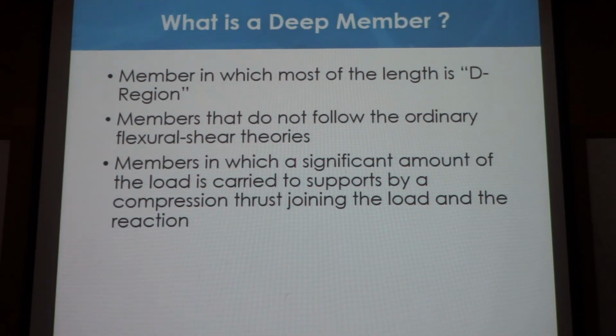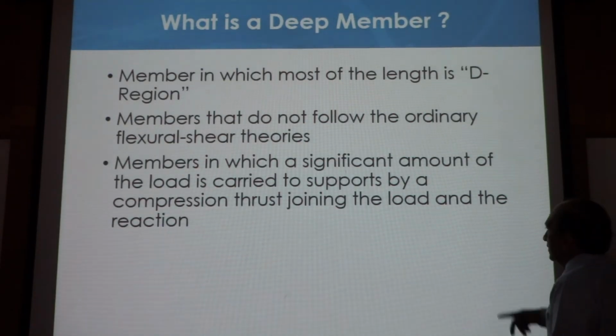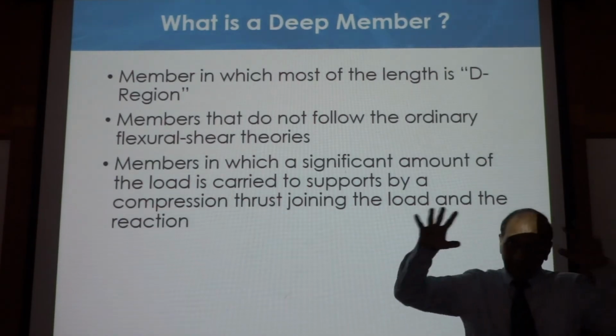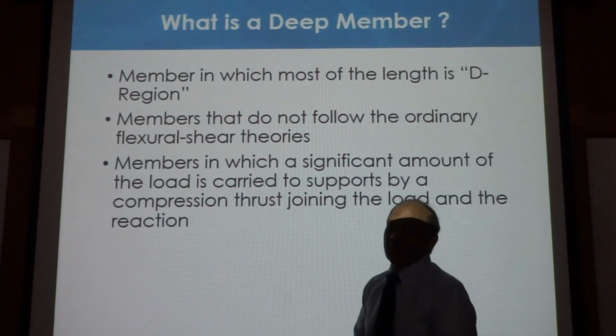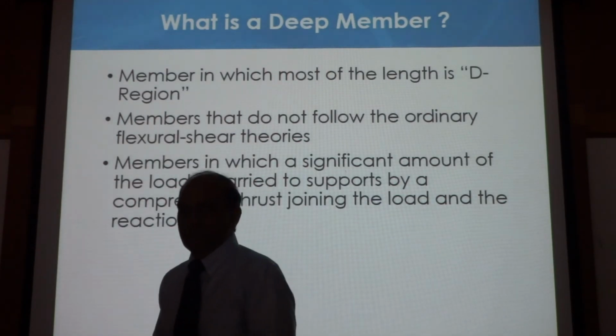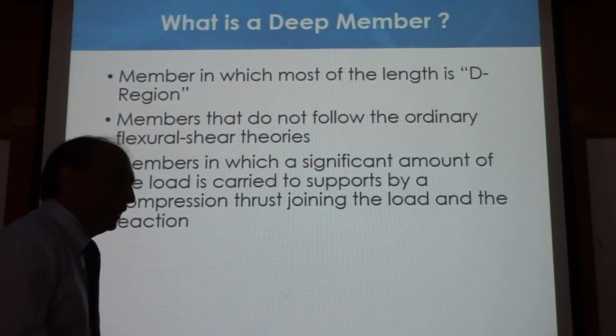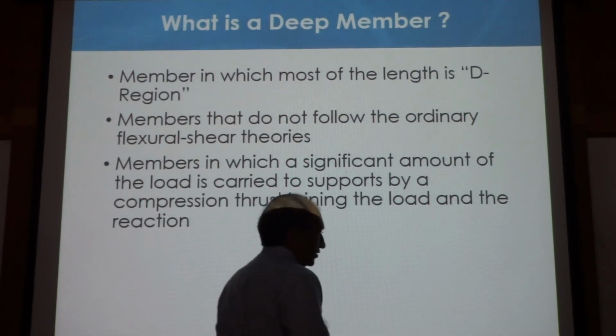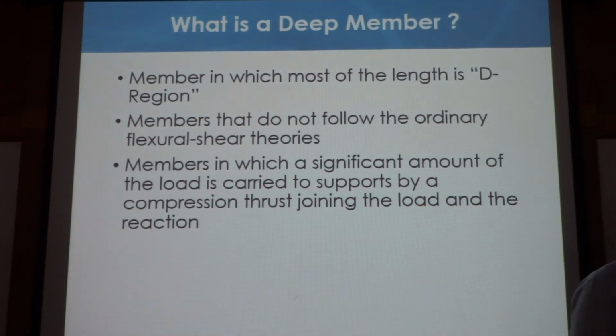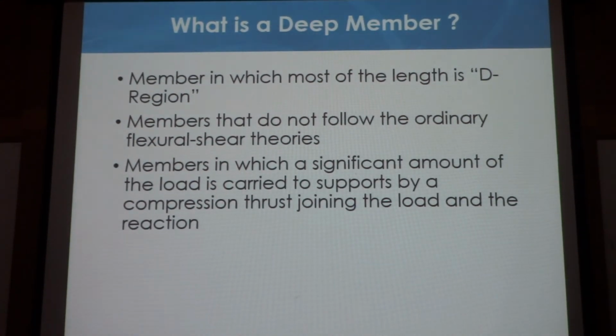So that is the definition of a deep member. Member in which most of the length is D region, members that do not follow the ordinary flexural theories, and members in which a significant amount of load is carried to supports by a compression strut joining the load and the reaction. These are some of the definitions of a deep member, right? Deep beam, walls, shear walls, footings, pile caps, brackets, many things.